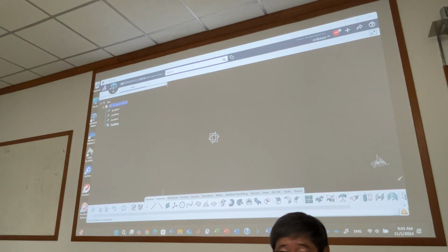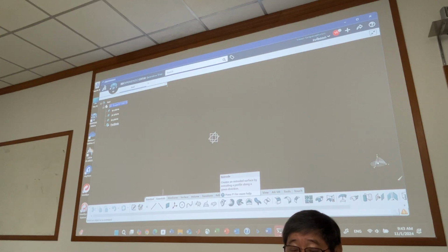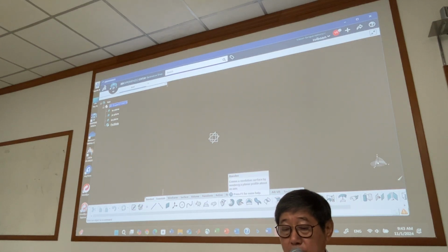Under essential, right? You have sketch plane. You can do sketch plane, no problems, right? You have this one, we call extrude. Look at this one. See, extrude, right? Is equal to pad. Extrude is pad anyway, but we call it extrude. You see, revolve is equivalent to shaft, right? Multi-section is the same. Fill,